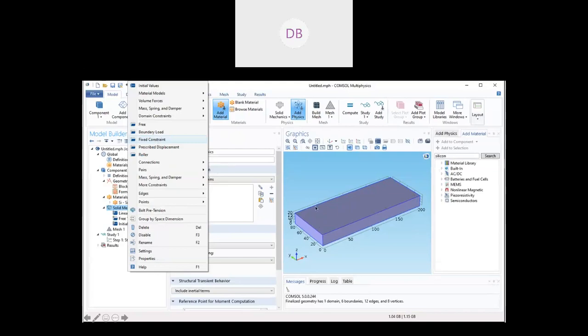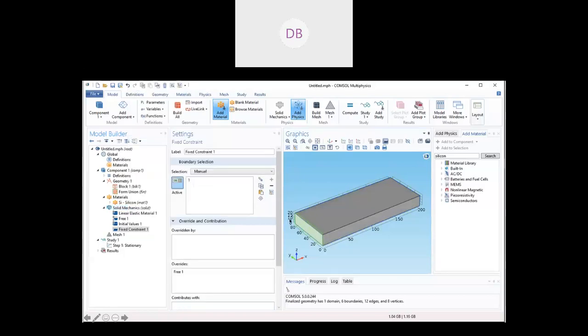So we select the fixed constraint. When we select the fixed constraint, we have fixed this edge. Obviously, it immediately shows a change in color. You can see. So this edge is 1. When we select, this edge is 1. So every edge is denoted by a number. So this edge, which we have fixed, is 1. There's a change in color, and obviously the same number will also appear here. So this becomes a fixed end. Fixed constraint is nothing but a fixed end we are talking about.